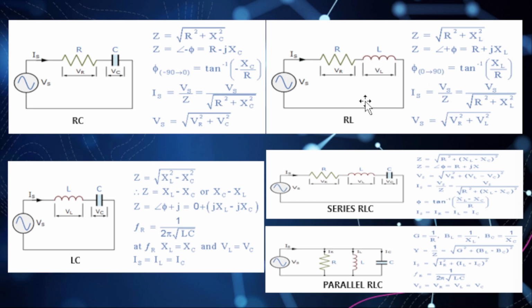With all the vintage radios I've done, you've heard me talk about how the audio transformer is often used as an RF choke as well. And that's to clean any DC from getting across your field coil and having an effect on your audio frequencies as they're reproduced. Or RF in general as well. You want to get rid of humming, etc. But anyways, digressing again, RL circuits are also used for low pass and high pass filtering of RF.